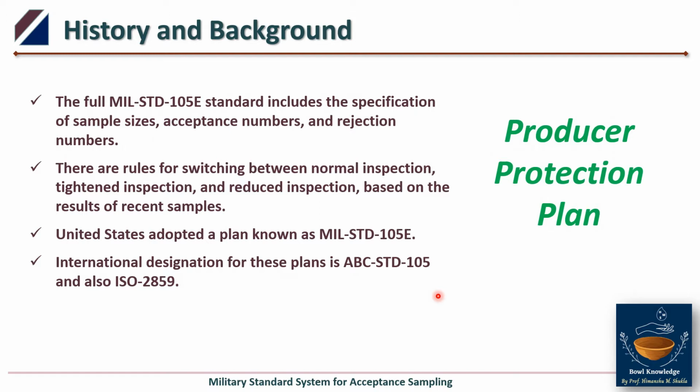So it is a progressively updating and self-correcting plan. That is one of the USPs of using military standard plans, because based on the samples which are already inspected and whatever the results are from the inspected samples, we can have the auto-corrected plan in real time. So in the plan which you have selected, let's say at an instant, after some samples, if you find it not fit for your use, you can update the plan. That is the provision provided under the framework of the military standard system.